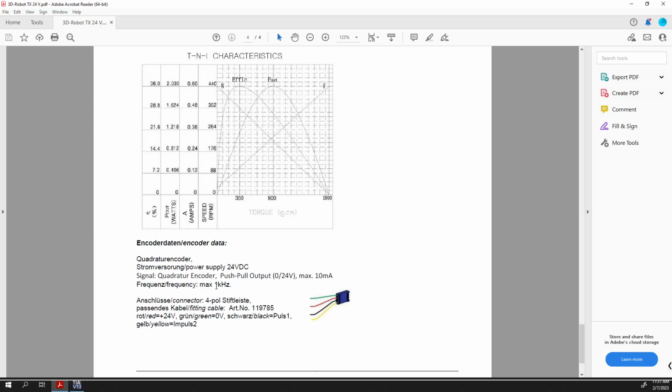Sometimes these are add-on modules. The 1769 Allen Bradleys we have up the hill don't have the capability for high-speed counting built in, but we could get a module that we would add on to it, so we actually would then have that capability if we wanted to. And that was my plan at one point, but that plan has gone by the wayside. So we've got the T-Mins, they've got it built in, and I think my new Micro 800s have it built in as well. So that's nice that we can do this with either one of those.